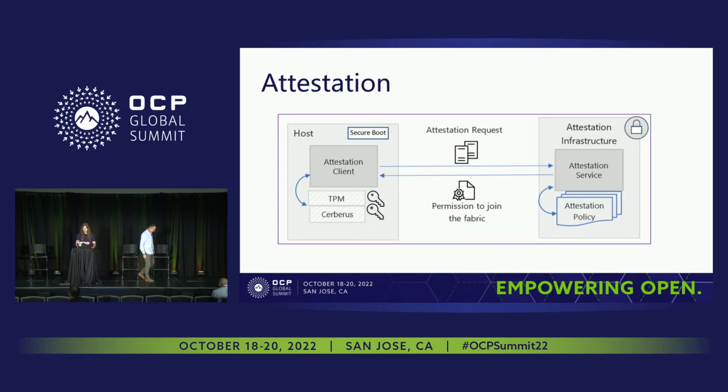Yeah. So this is a really high-level view of how the attestation is performed on the BMC. With the root of trust internal to the BMC, it's a combination of the root of trust and also it uses TrustZone a lot for the fTPM stack, which is kind of big, so we don't put that whole stack in the root of trust. Instead, the TPM APIs run in the TrustZone, but they call down through a mailbox interface to the root of trust.